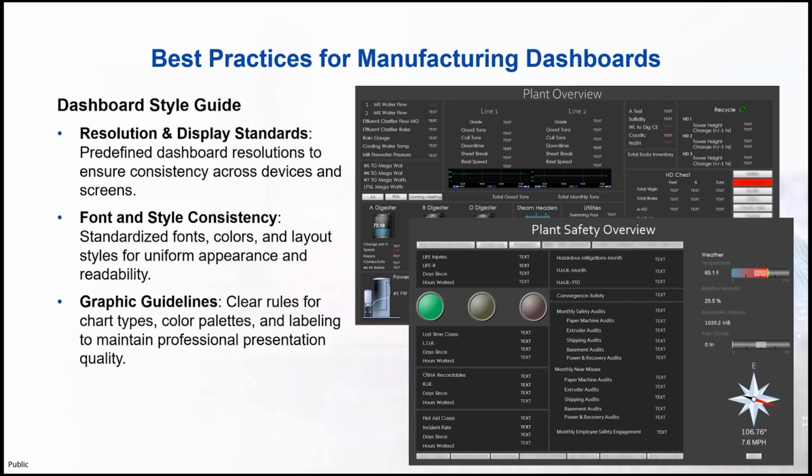Another way to promote readability and consistency across graphics is by choosing a certain design or style for graphical objects. Whether it's 2D or 3D, having consistent styles can help read data consistently. For example, Parkview has quite a few different gauge options. Some are full circles, some are half circles, some change colors, and others don't. So by having consistency across your gauges, people don't have to learn what each type of gauge means and how to read it. They can look at it and instantly know what data they're looking at.